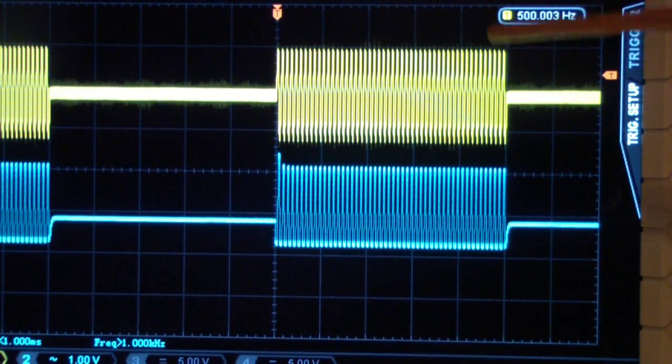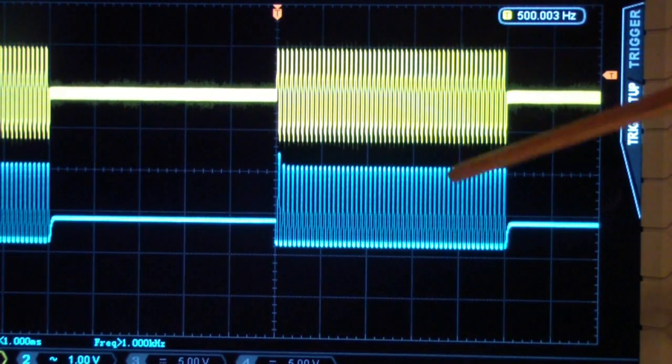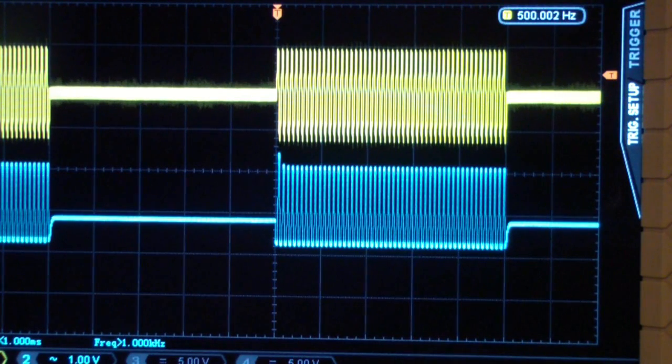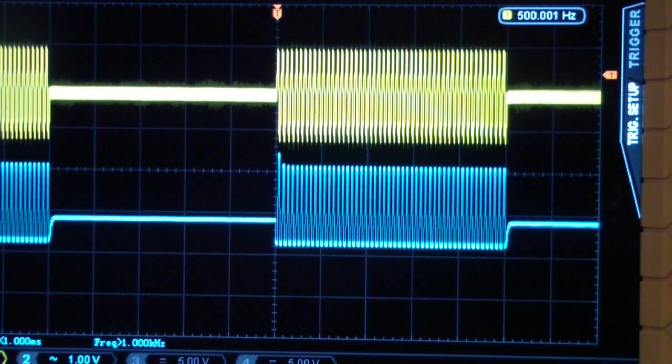I suggest adding tone burst to the tests you do, the electronic tests that you do on amplifiers, music amplifiers. But that doesn't replace the use of sine waves, including frequency analysis, Bode plots, and those sorts of things, as well as square waves to look at transient response. So what you see here is an example of the kind of distortion that you might miss in a regular sine wave analysis, but in a tone burst you might be able to see it.